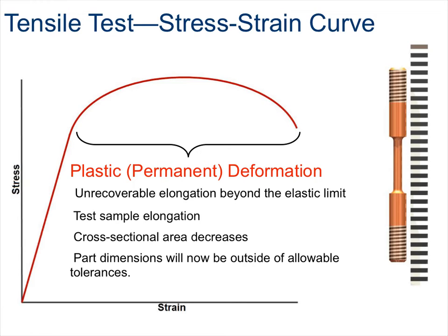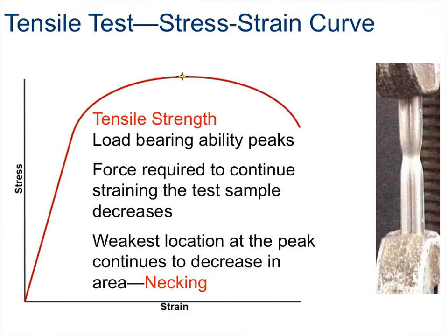Plastic deformation is characterized by a noticeable amount of unit strain with relatively little increase in stress. As this occurs, the material becomes harder. Eventually, the material reaches its ultimate stress, which is the ultimate amount of stress that a material can withstand without failing. Beyond this point, the material will exhibit necking, which is a visible decrease in cross-sectional area at the location where fracture will eventually occur.